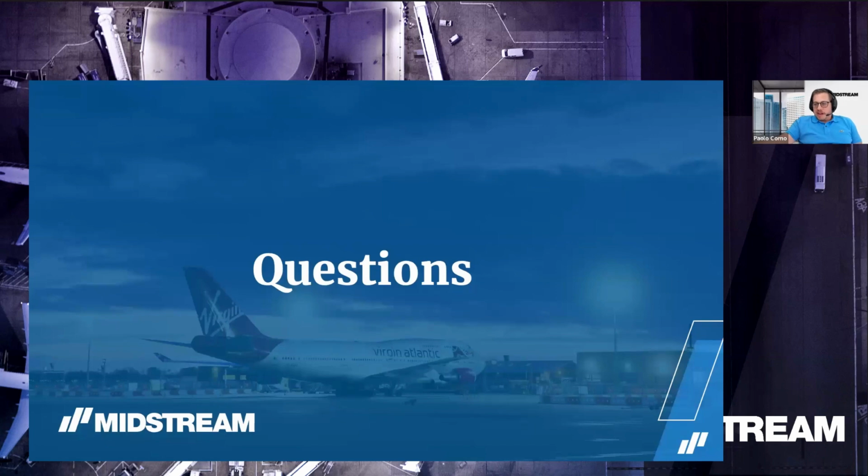Exactly. It is never the correct way to set it to 1, but effectively it's doing the same thing. So, if I have 20 lux with a maintenance factor of 0.8, and I say, no, I want to be more sure, do it at 40 with 0.8, it's the same thing as doing it at 20 with 0.4. That's exactly what the maintenance factor does to a simulation. This is also why simulations with different maintenance factors are not comparable, because it's like comparing a simulation done at 40 lux with one done at 20 lux. You expect one to have double the lights and double the power.